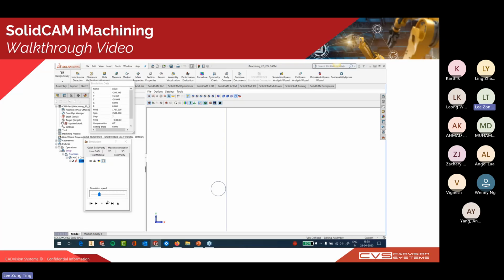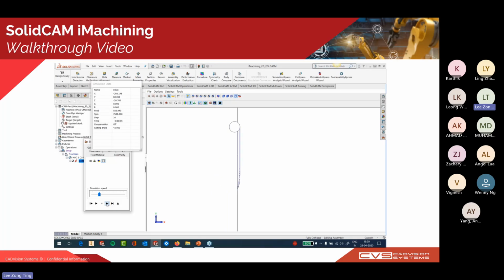You can see the feed rate and spin rate vary when the cutting angle changes during the machining operation. When the cutting angle reduces, the feed rate will increase. This is to ensure there's a constant force on your tool to minimize tool breakage and greatly prolong your tool life.